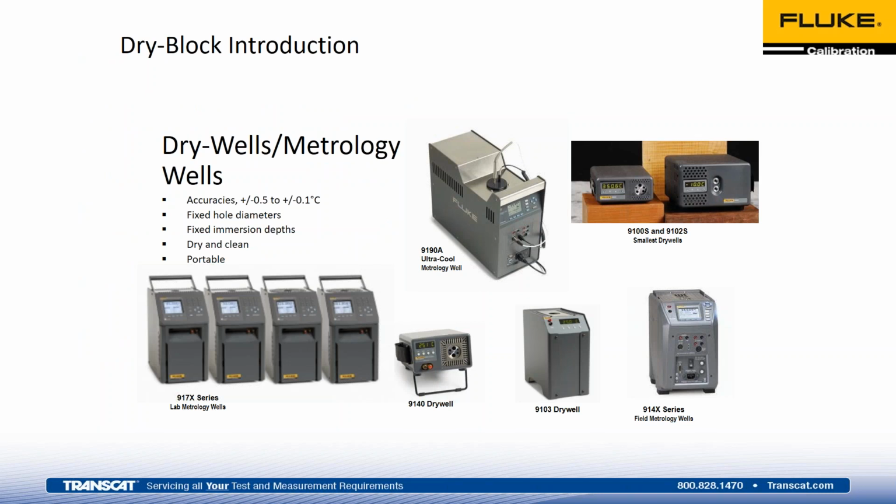So basically, what is a dry well? Well, it's what it says there. It's a heat source. You can think of them like an oven, but a very, very accurate oven. Most of them have some sort of a block assembly or insert that will heat or cool to a specific temperature. The accuracies on dry wells can range from several degrees to very accurate, to tenths of degrees. Again, on the block design, some of them are fixed, some of them have what they call a block insert design where one is removable and exchangeable.